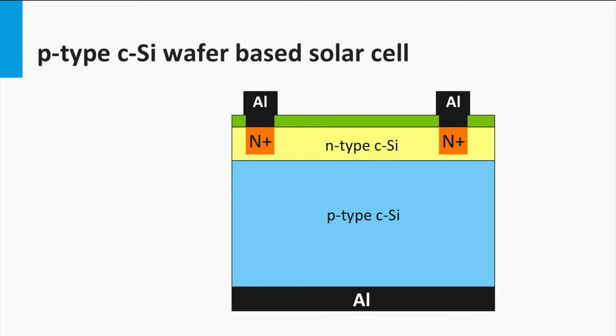At the back surface of the solar cell, we have similar issues playing a role. As the electrons are collected in the N-type layer, the holes are collected at the back contact. As electrons are the only charge carriers that exist in a metal, you have to realize that the holes recombine with the electrons at the contact interface. If the distance between the PN interface and the back contact is smaller than the typical diffusion length of the minority electrons, the minority electrons can be lost at the defects at the back contact interface due to Shockley-Read-Hall recombination. How can we reduce this loss mechanism?